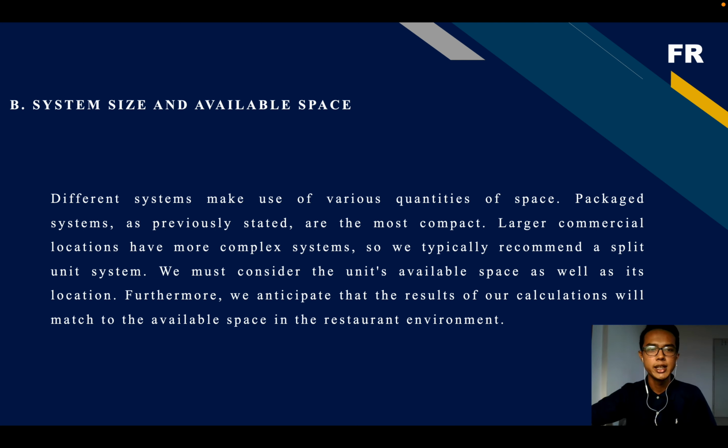B. System size and available space. Different systems make use of various quantities of space. Package systems, as previously stated, are the most compact. Larger commercial locations have more complex systems, so we typically recommend a split unit system. We must consider the unit's available space as well as its location. Furthermore, we anticipate that the results of calculations will match the available space in the restaurant environment for our project.